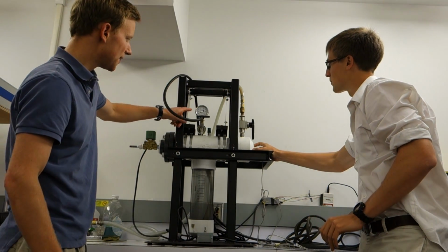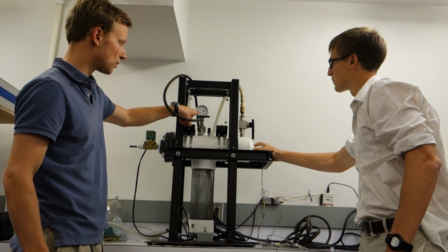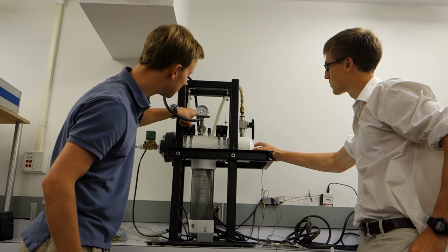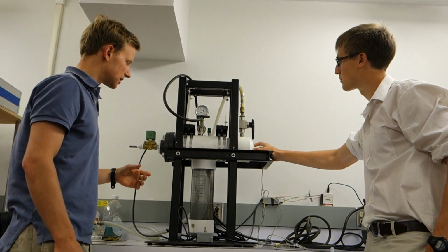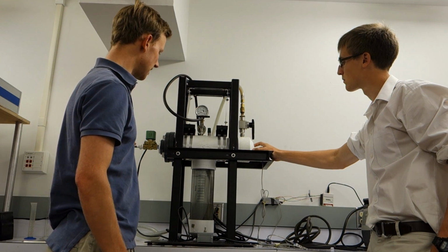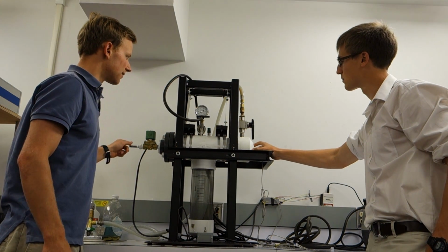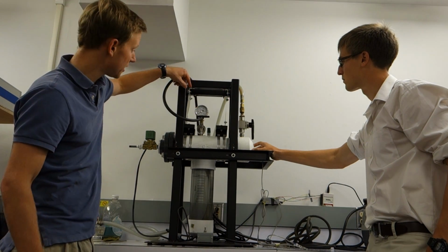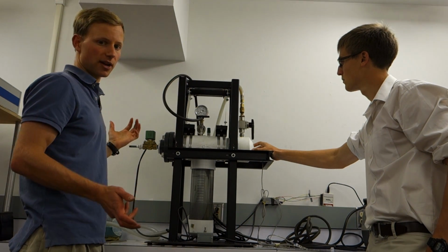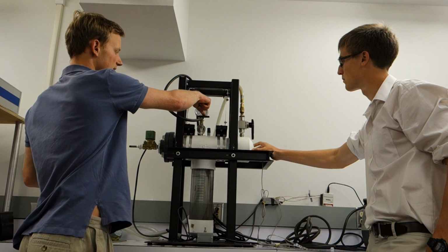And we'll notice right away that the pressure on the pressure gauge went up. It's about 8 psi right now. That's because we just displaced or compressed some of the air inside because we have a closed system. So next step is we need to pressurize the air the rest of the way. We're going to pressurize up to about 40 psi. So we've got to open up this hose here